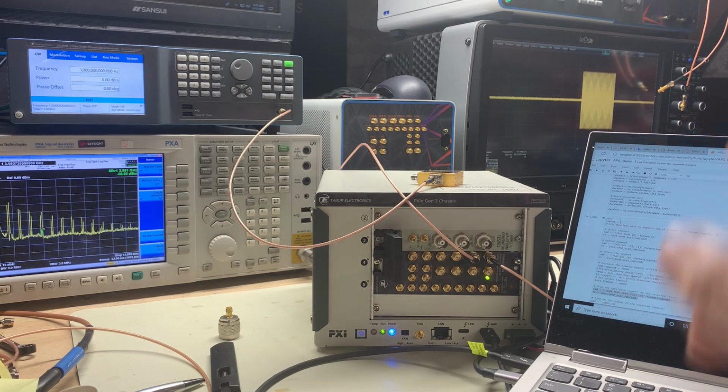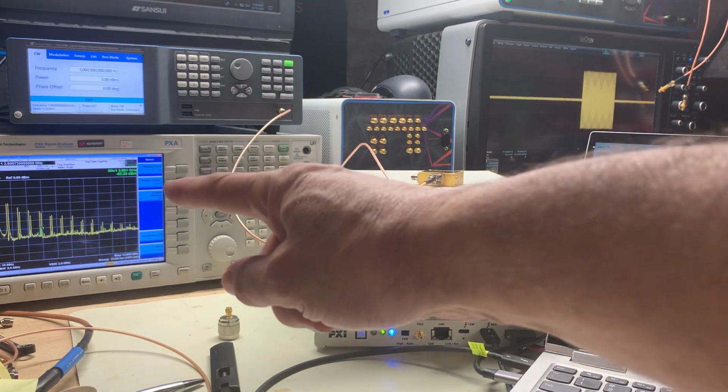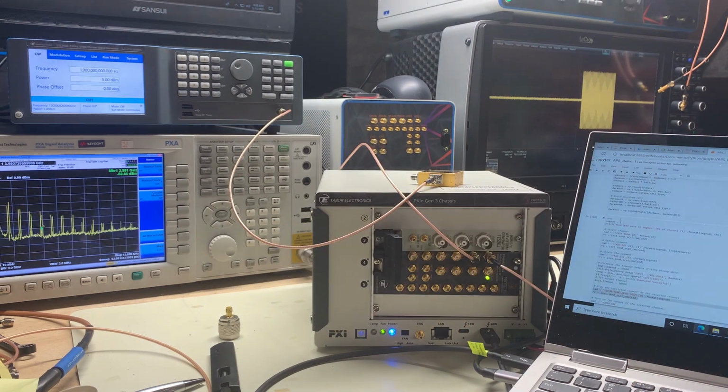And there you can see on the scope we have a pulse. So the pulse is 2048 points long, so that equates to 70 megahertz with 75 megahertz, as I set the sample rate currently to 1 gigasample with the arbitrary waveform generator. And then on the spectrum analyzer, you can see the signal all the way out to 13 gigahertz over here, and that represents the different Nyquist zones of the instrumentation.